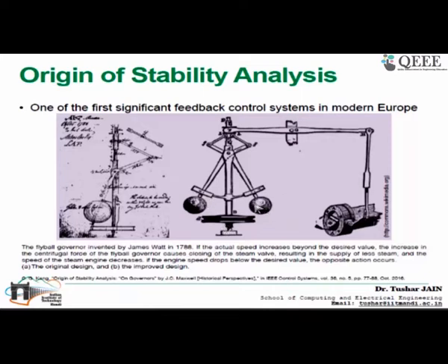The basic function of this governor is that when this disk D starts rotating, these 2 balls move apart from each other. Whenever they start expanding, this pulley will pull down, and in turn this other pulley will turn up, and then finally closes this valve. So this is basically a control as well.